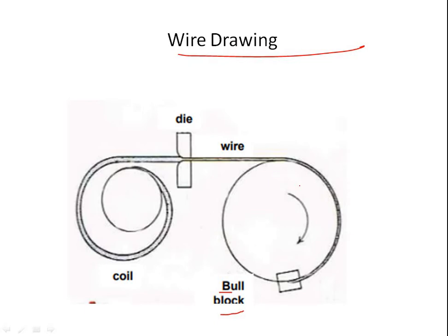The lime neutralizes any acid and serves as an absorber and carrier of the lubricant during dry drawing. The lubricant may either be grease or soap powder. For wet drawing operation, the die itself is immersed in the lubricant.